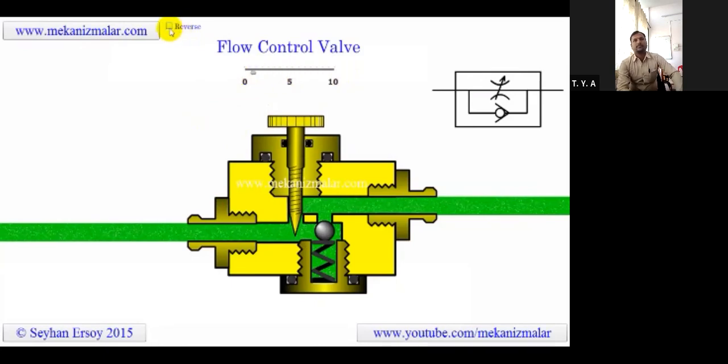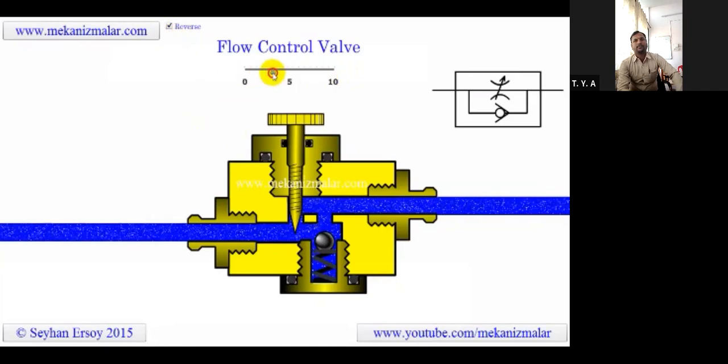On the other hand, the reverse flow goes over the check valve and needle valve combinations. This prevents the fine-tuning of the return flow, since we do not have any control over the flow passing through the check valve openings.